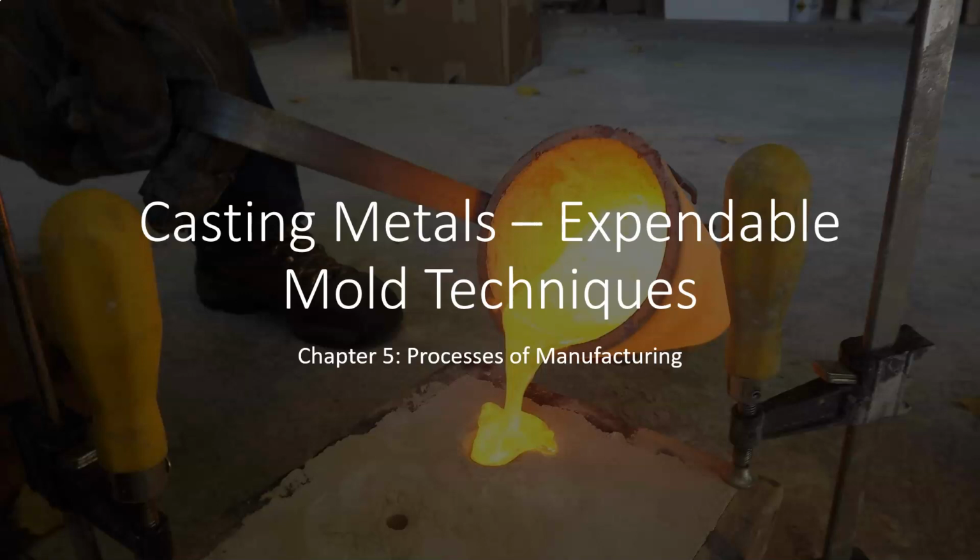Okay, so expendable mold techniques, or expendable molds, are basically molds that you're going to build for the purpose of that single casting, and then the molds are going to be destroyed when you get the part out of that mold. After the part has cooled and solidified, you have to destroy the mold in order to get the part out. And then if you want to make another part, you have to remake the mold. So these are expendable mold techniques.